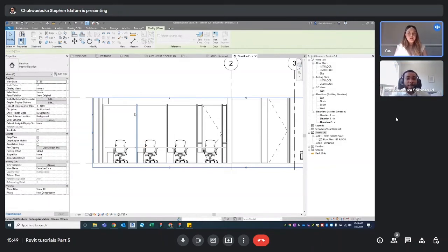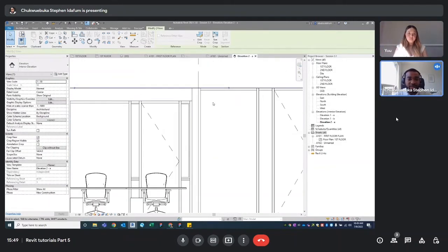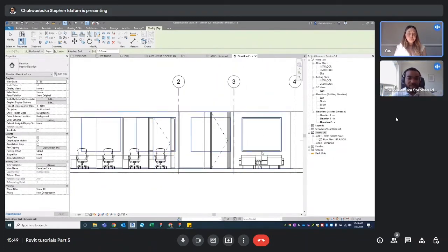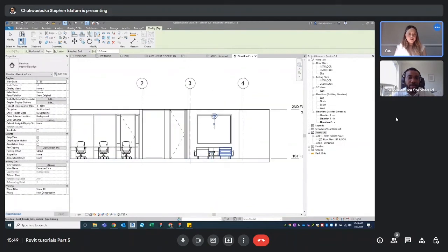What does tag mean? Creating a tag, for example, TG, lets you tag the mullions or the curtain wall. The purpose of tagging is to know the specificity of what is inside your plan. For example, if I want to get furniture for this plan, let's say we're actually going to build it, we need Revit tags to know the amount of a specific kind, and an amount of a different type of it.